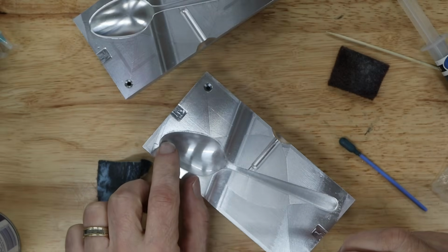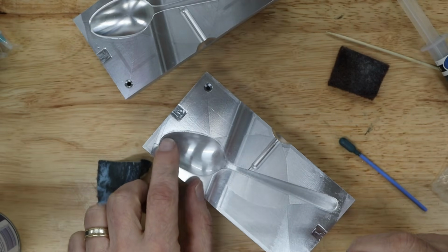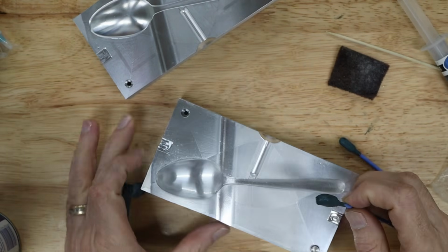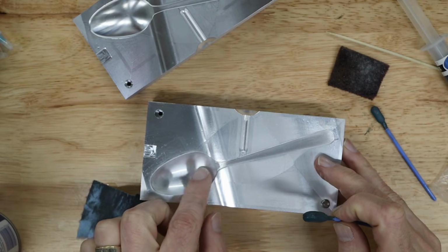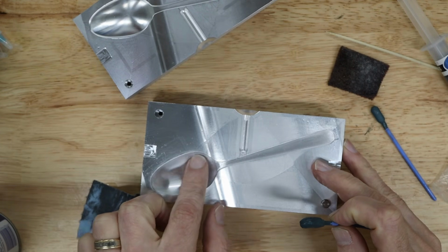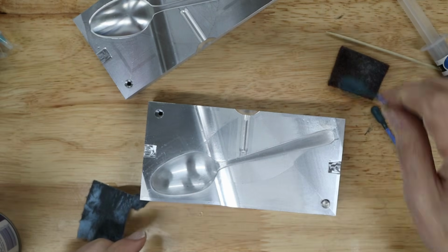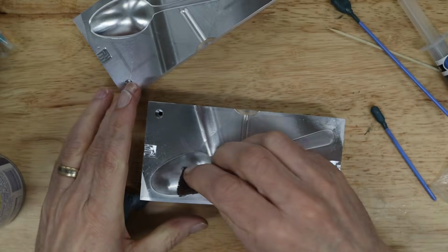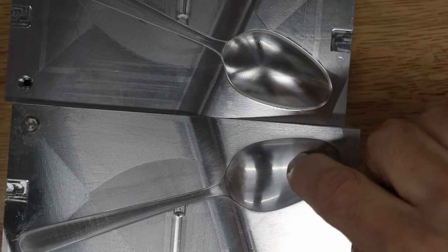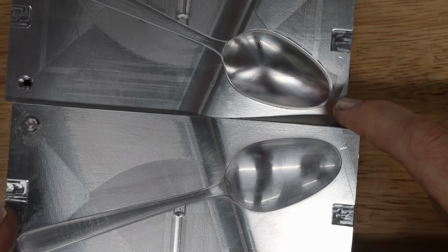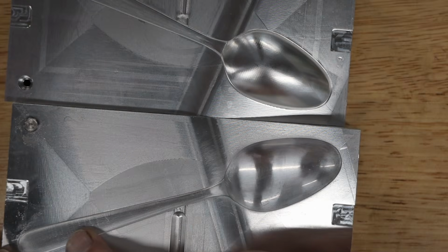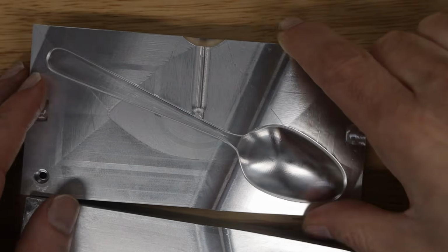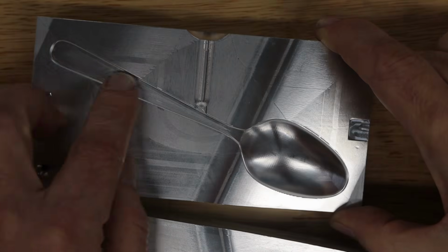Okay, I'm seeing some tooling marks still up there, so I'm going to use some Scotch-Brite on that. And there's a few shadows of tooling marks along there, so I'll give that another shot as well. Here you can see the difference between sections that I've sanded and polished, such as here, versus this section here, which still has the tool marks.